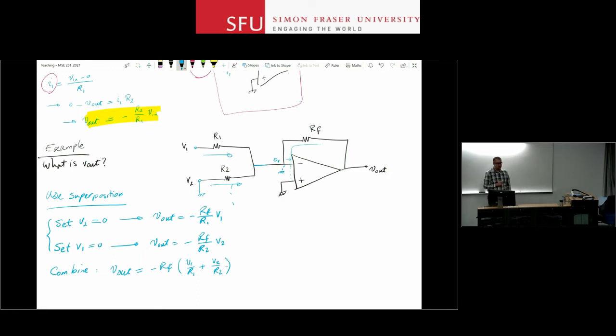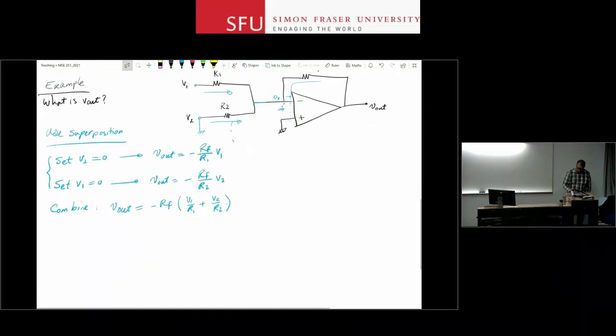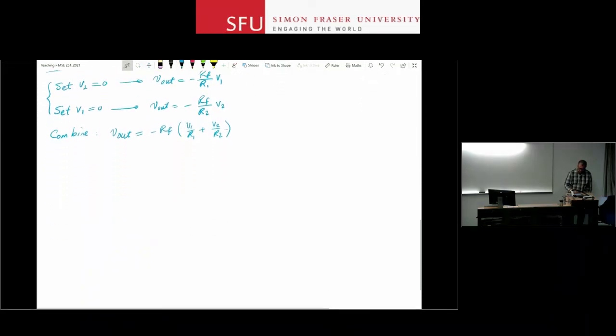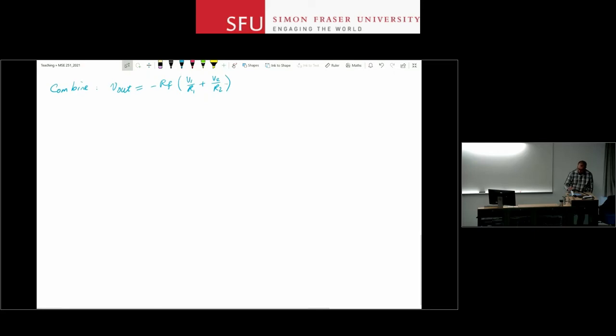that is proportional to that current. So again, it is helpful to think about having that virtual ground and a resistor somewhere as a way of generating a current that is accurately representing your voltage signal.